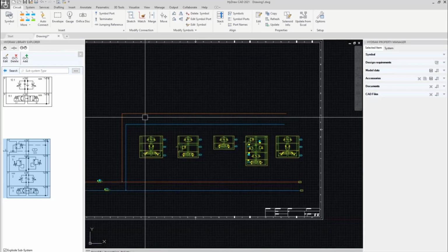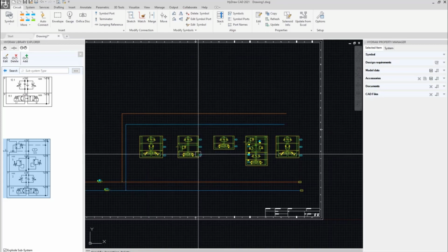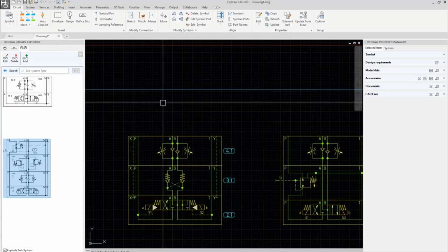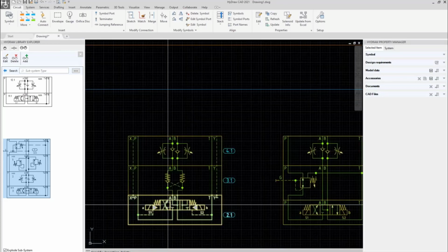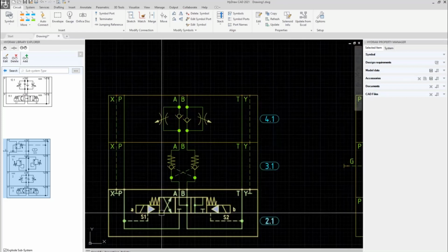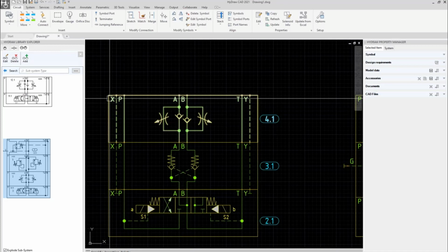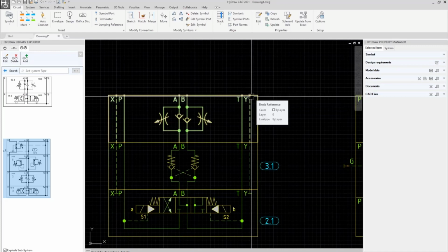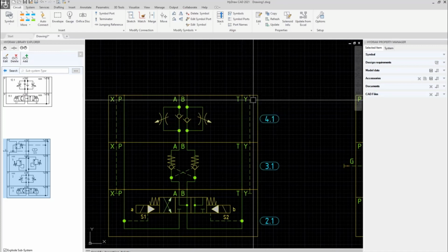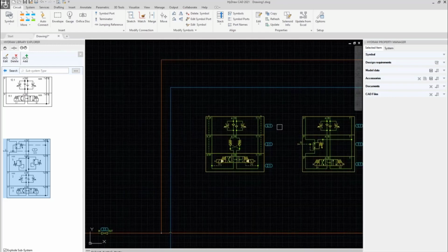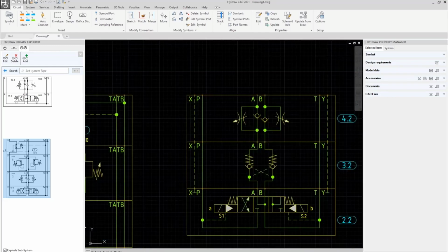Now our valves will be connected to the pressure line. So we start making the connection. As you see, I have selected the internal pilot valves NG16, so I need to close X and Y. So to describe that you don't need X and Y, we use the terminator. So the terminator will be applied to the X port and Y port. And the same we do on the last element, X port and Y port.